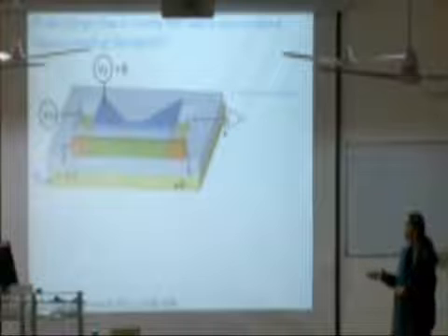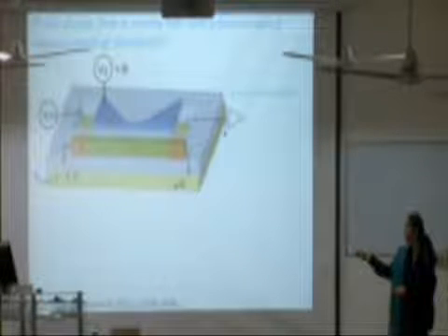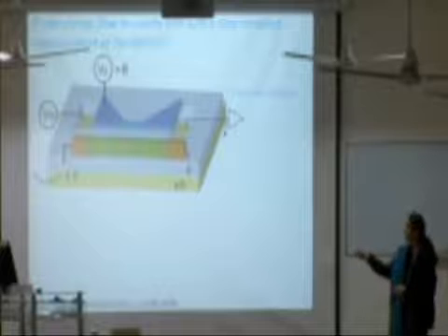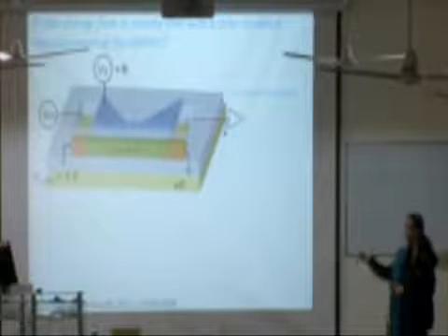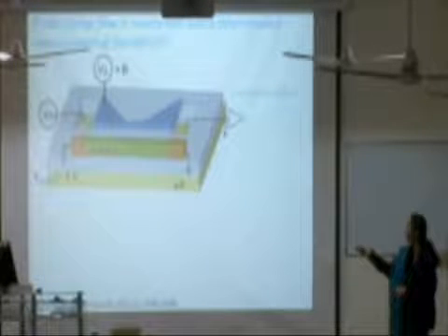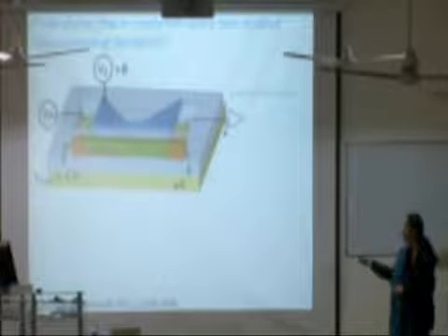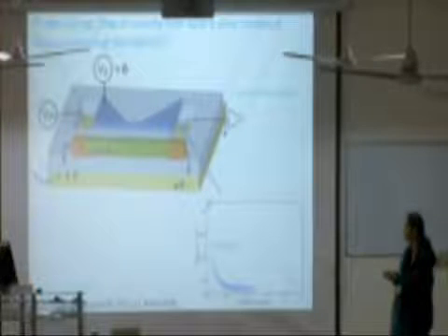Our experiment consists of applying a voltage pulse to one of these electrodes. The amorphous germanium strip, shown in green here, is connected to the gold electrode. We start pulsing the gold electrode, and as we apply a voltage pulse, charge diffuses through the amorphous germanium strip, and we see that motion. And then we monitor the conductance of the MOSFET as a function of time as the charge diffuses.